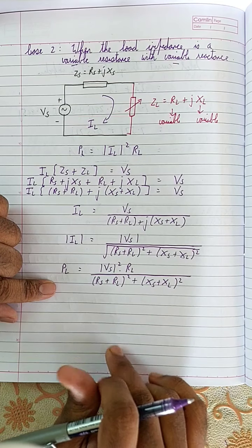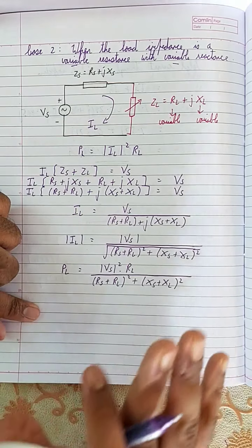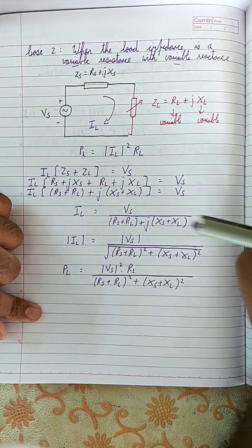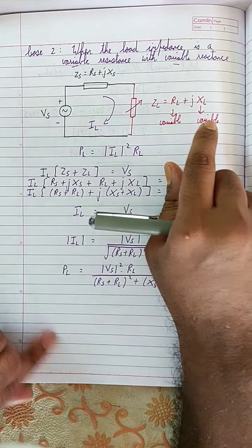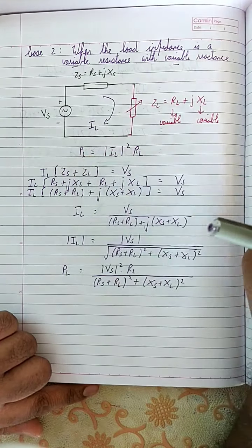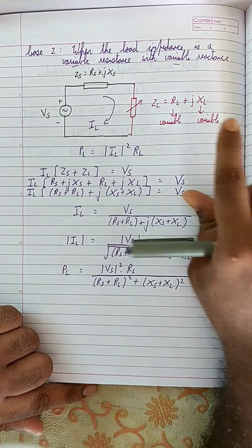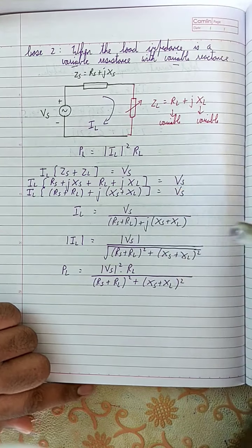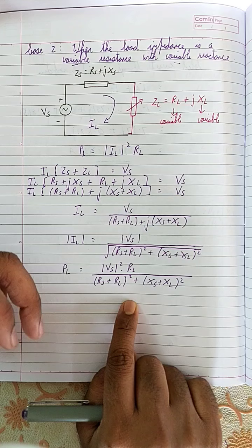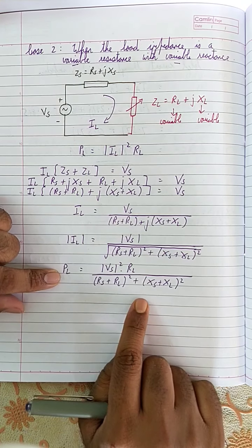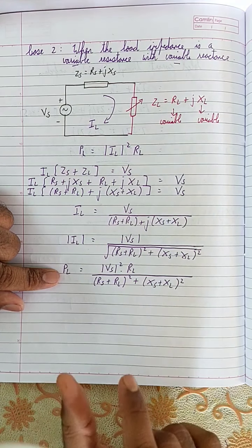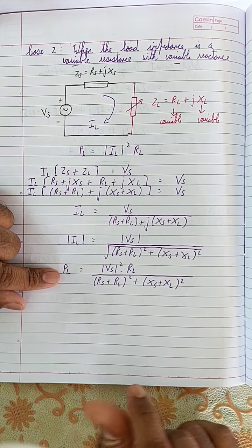Okay, so one of the easiest things to understand about this is that both the terms are variable. This is variable, this is also variable, but this is the value you need to find, right? You can't change this, because if you change this, you are basically changing the value of the power. So you are going to change this one, but you can change this, right? This is a variable reactance, and if you look very carefully over here, if you want to have maximum power from the circuit, then this denominator must be very small, or you should change the value of the denominator such that it can be small.